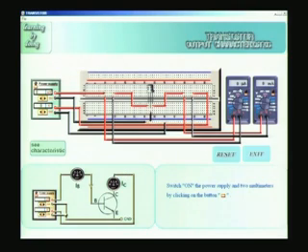Now, there are 2 multimeters on your right. The first one is measuring the base current. If you follow the 2 curves, you can see it is connected here with the base supply. It comes in series with the base and the emitter junction of the transistor. Similarly, on the collector side, I have one more ammeter, the multimeter used as a milliammeter, and that is for measuring the IC, the collector current.